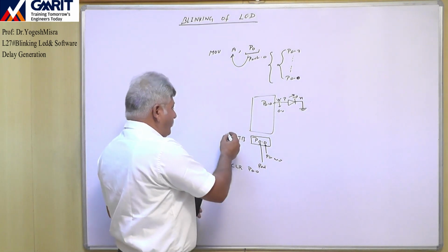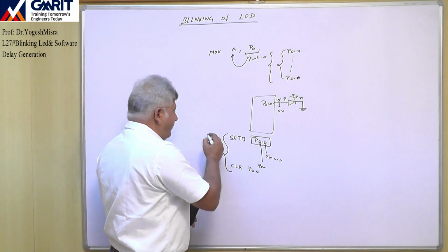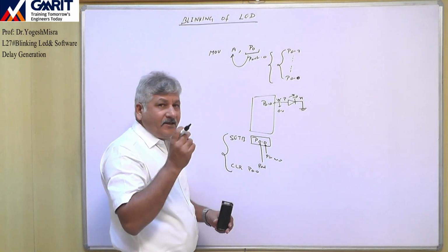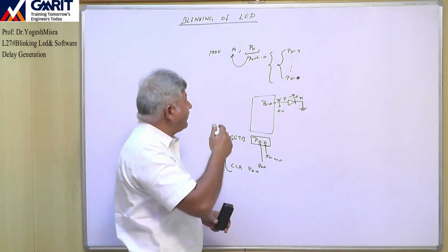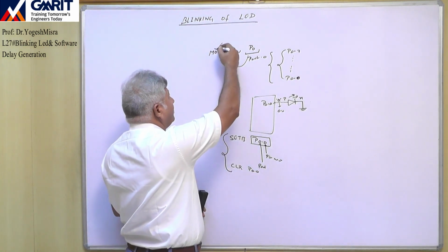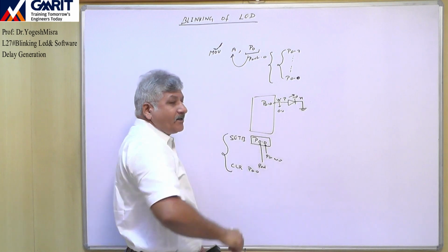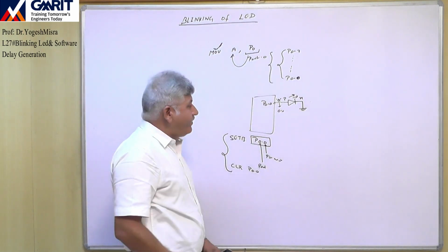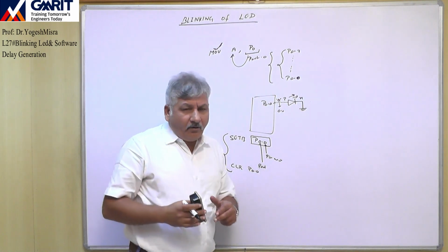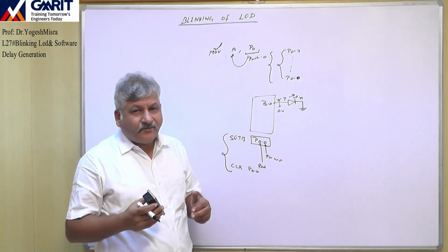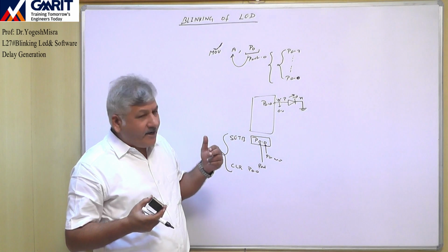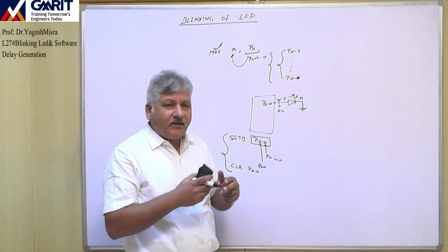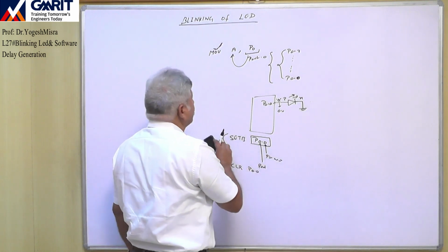So these two are bit related instructions, right? With these we are accessing a bit of a particular port, whereas this other one is a byte addressable instruction where we are accessing all the 8 bits of the port. So for all 4 ports, we can access any pin of all these 4 ports, or we can access the ports in themselves also.